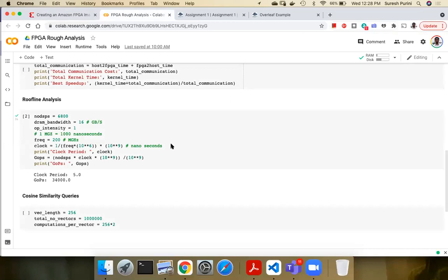on FPGAs, we use DSPs, while LUTs are also used for doing the computations, especially since they give the reconfigurability. These DSP units do floating point multiplications and additions, and fixed point multiplications and additions.